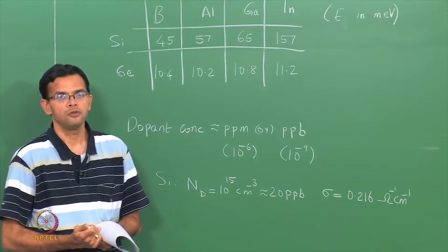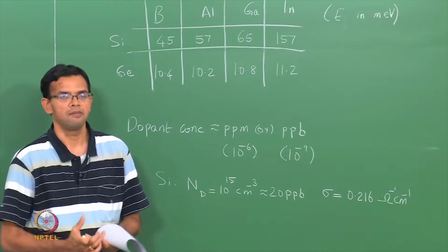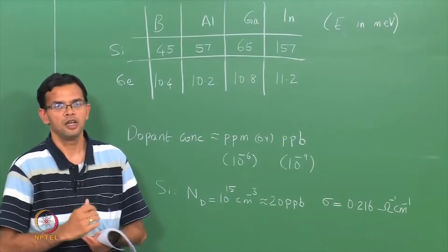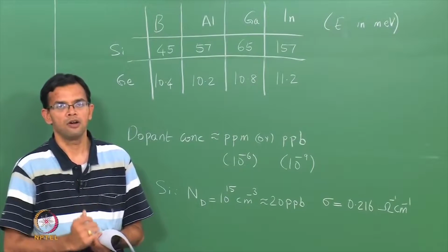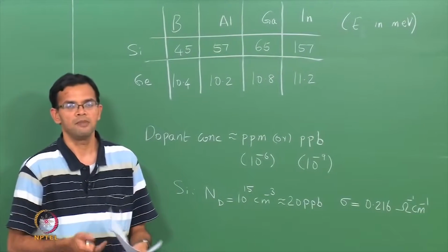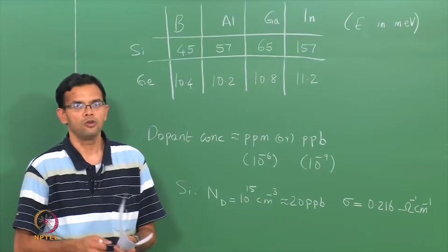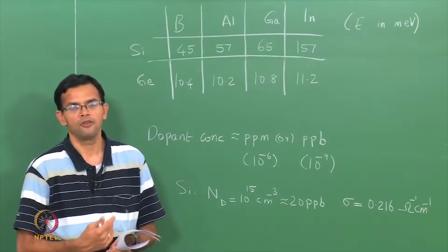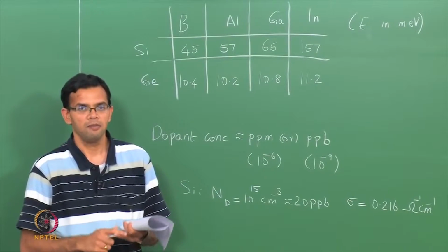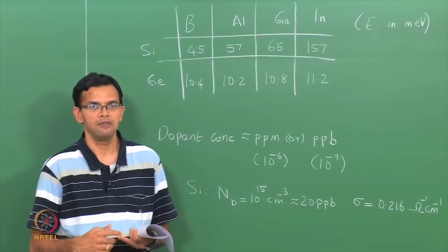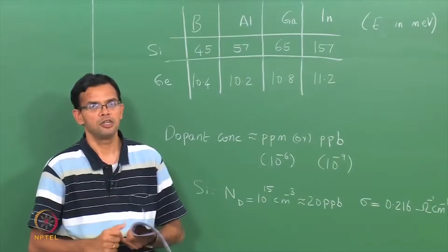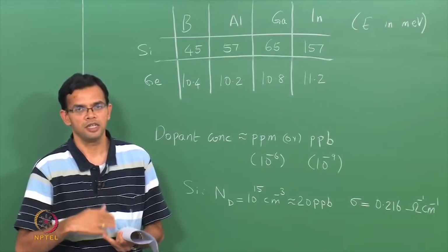Typically, we have the sample at high temperature, and you have a carbon source, so that the carbon then just diffuses into the surface and into the bulk of your steel. We can do something similar in the case of doping in semiconductors as well. If you want to dope n type, you have a source of your n type material. This could be in the gas phase, or these could be ion implanted onto the surface. We will see what ion implantation is later, so that these can then diffuse into the surface and from the surface into the bulk.